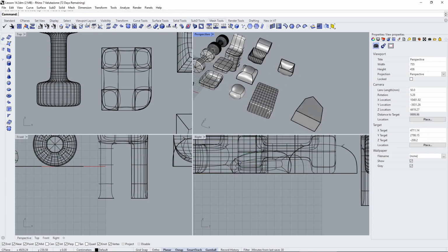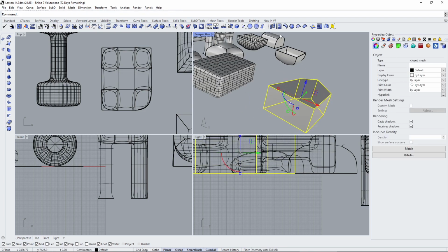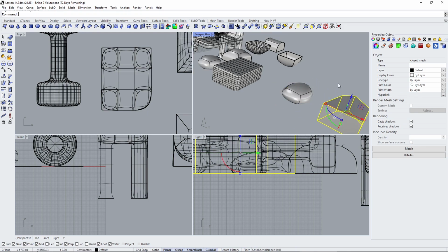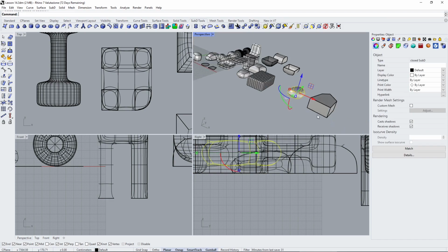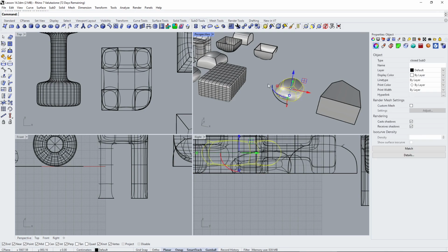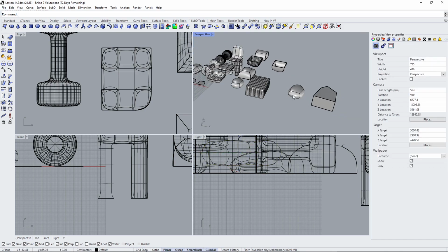By the way, you can also extrude using the mesh tools. And again, let's convert this into a SubD. Press enter, move this one aside, and that's the result. Again, because we have so few subdivisions, it's gonna look really rounded, and then we can work on that as we saw before. Now let's finish with these selection modes here.